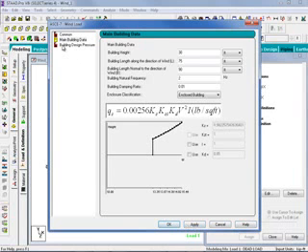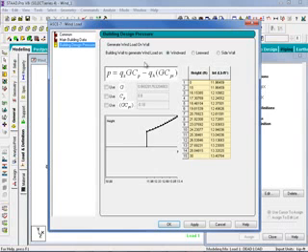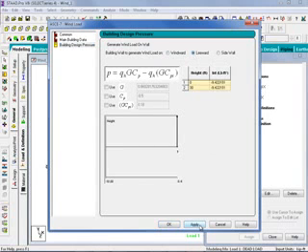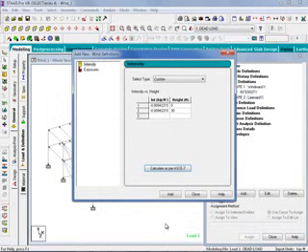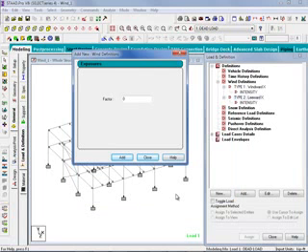This time, when I select the Building Design Pressure option, I'm going to select the leeward wall, and then I'll click Apply, and then I'll click OK. I'm going to complete this process by clicking Add, and then I'm going to click Close. For this particular structure, again, I'm not going to consider any exposure factor.